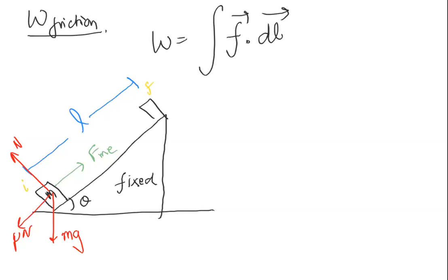Okay. So let's calculate the line integral of friction. First, we divide the path into elements. Here are the elements. Actually, I could have done it in one arrow, but okay, I made three. Next, I have to draw the forces, and since I'm only finding out the work done by friction, I'm not bothered about the work done by me or by gravity.